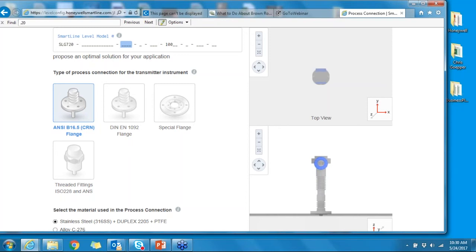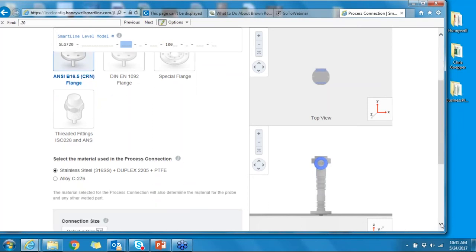So someplace in the specification phase of the project, somebody had missed the measurement. Short story is somebody had to order out an adapter. So we got the adapter, got it installed, had to make some changes during setup for blocking distance, and away we went, and it started up just fine. So very, very important when you select your flange to know what's going to be on that tank, so that the flange can be matched for the instrument when it arrives.